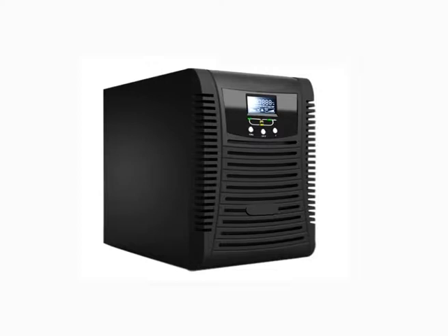And the third type of UPS is the online UPS. As you see, the term online UPS most typically is synonymous with the term double conversion. Online UPS are so named because the output inverter supplies 100% of the current of the critical load. The name double conversion UPS arises from the operation of the device.